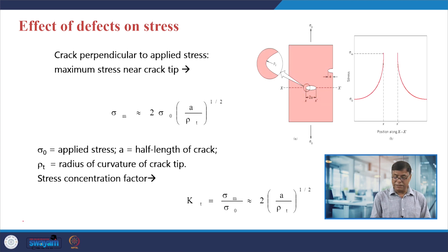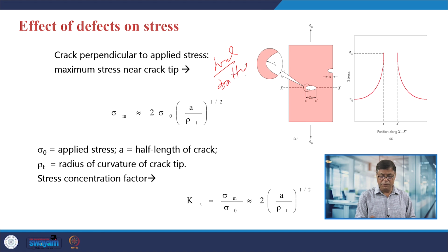In case of cast irons, particularly grey cast iron, it is very hard, brittle and has very low ductility. Because of this combination of properties, if there is a defect, it will cause high stress concentration, the crack tip will remain sharp, and the high stress concentration will trigger the growth of the defects, easily causing catastrophic fracture without much indication.